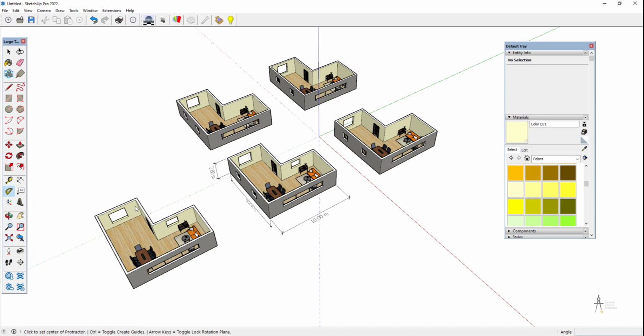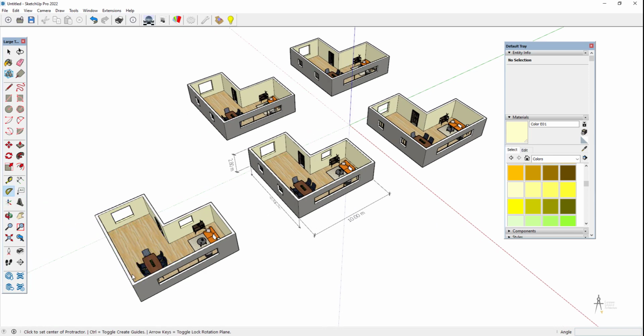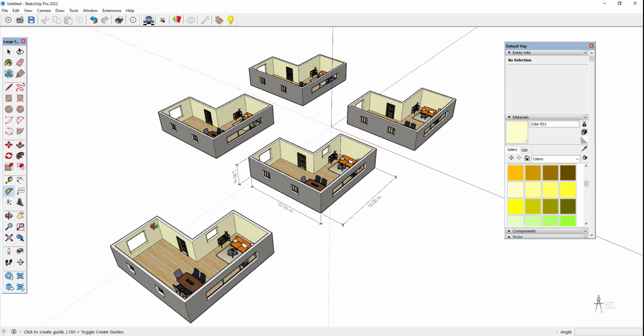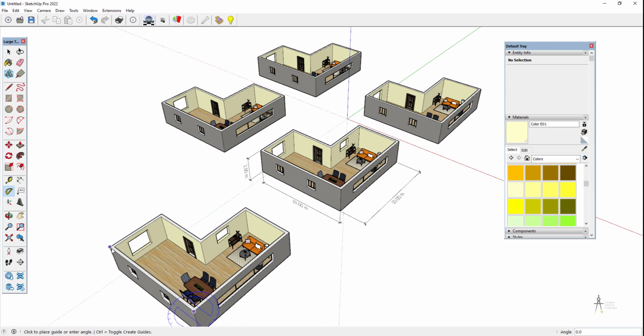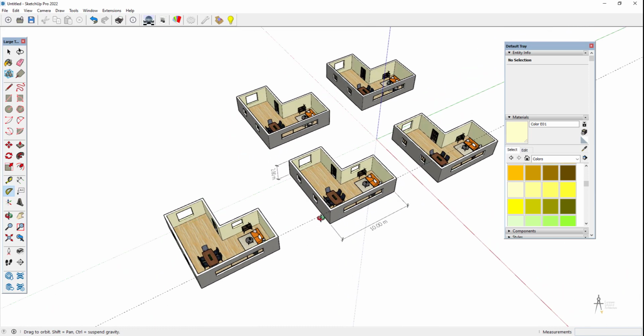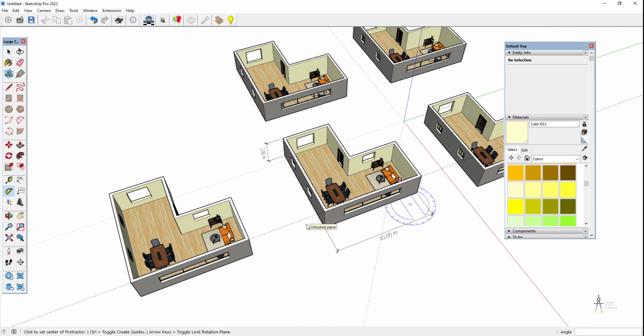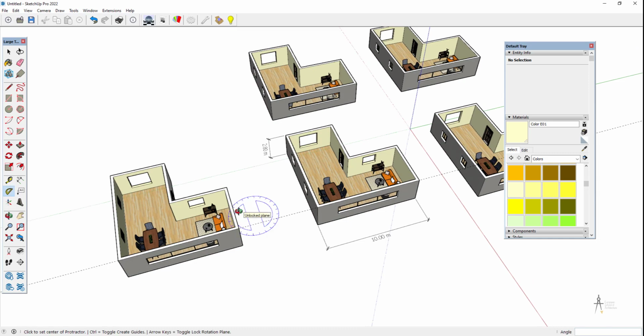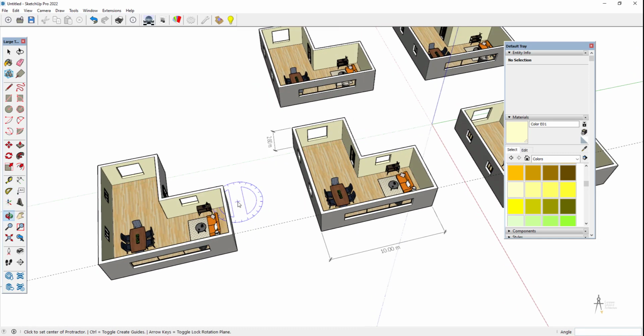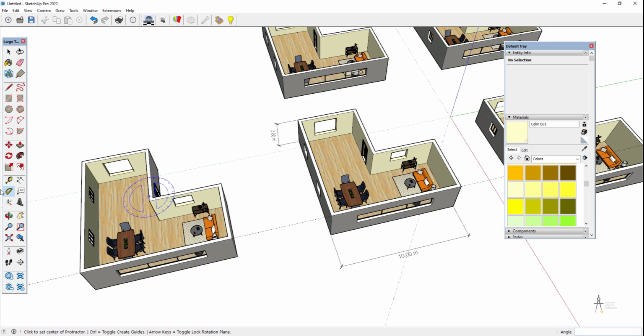So I click on it, I select a point from which I want the angle to measure, and then I have to select another 2 points. So if I go for this one and this one, here at the bottom corner is going to say 90 degrees, okay? So you need 3 points to measure an angle, and the first one's going to be the vertex.